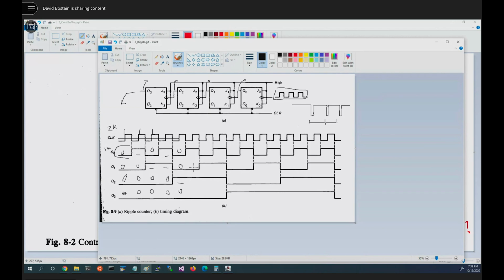For example, in the last one where I said, let's only move the data from X into D only when it's the second clock, well, we would recognize it being the second clock because that number is 0, 0, 1. If we had the 4 phases of the clock available to us, we would know, okay, here's where we need to enable the load signal in order to make it happen. Now, clearly, we'd have to deal a little bit with the timing because we've got a rising clock rather than a falling clock in the middle, but we could certainly flip that to a not clock easily enough.